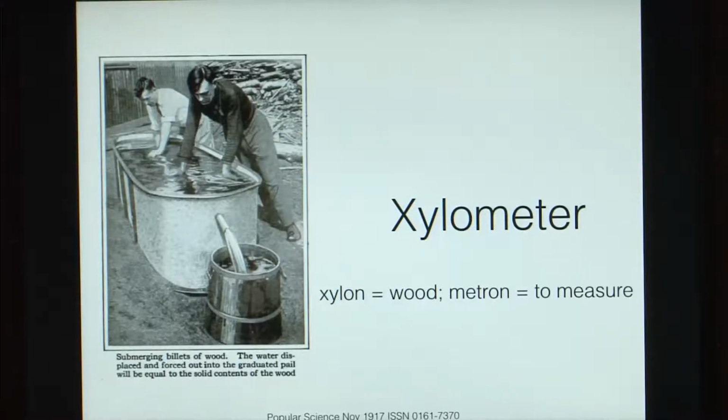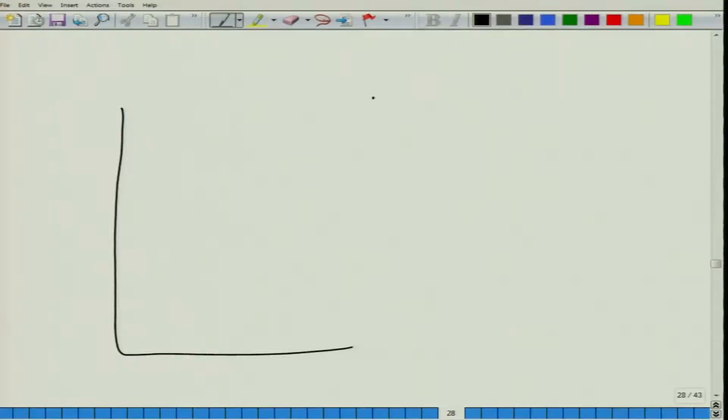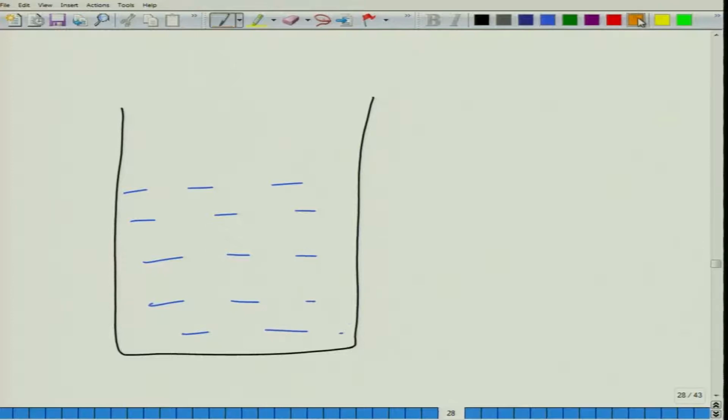There is one other way of measuring density in which we can take this density directly from a sample that is floated into a liquid. So how do we do that? Let us again consider a beaker in which you have some amount of water and you also have a sample of your wood that is floating here. So consider this to be a floating sample.